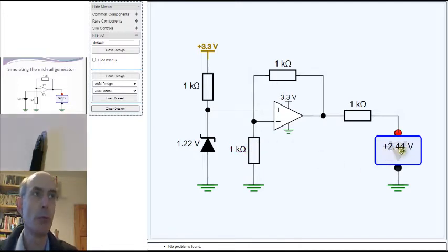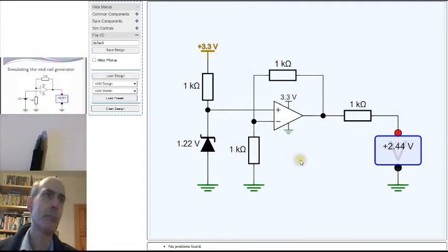You get 2.44 volts. It's also suggested that the resistance values that you use are somewhere between 10K and 100K in the lab script. And that's due to the fact that using lower value resistors increases the current, and that just wastes power, really. Using any higher values than 100K makes the circuit a bit noisy. We'll talk a lot more about noise in the summer term.